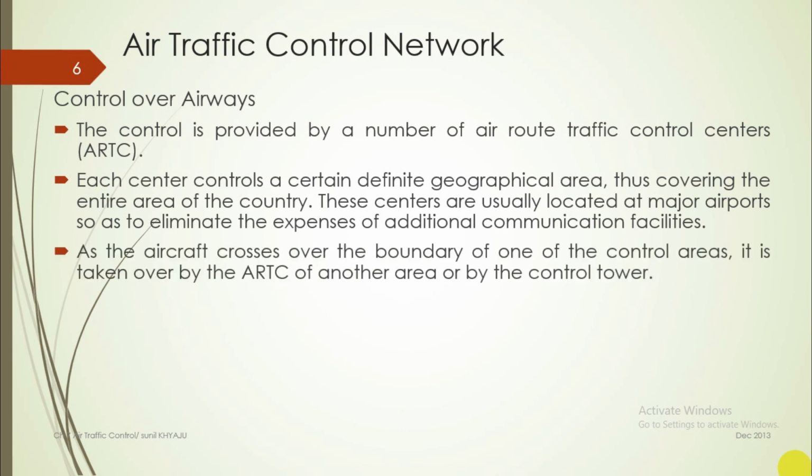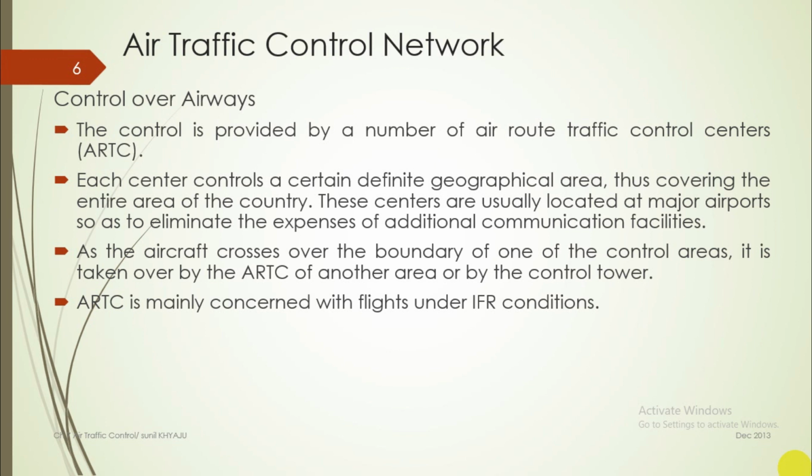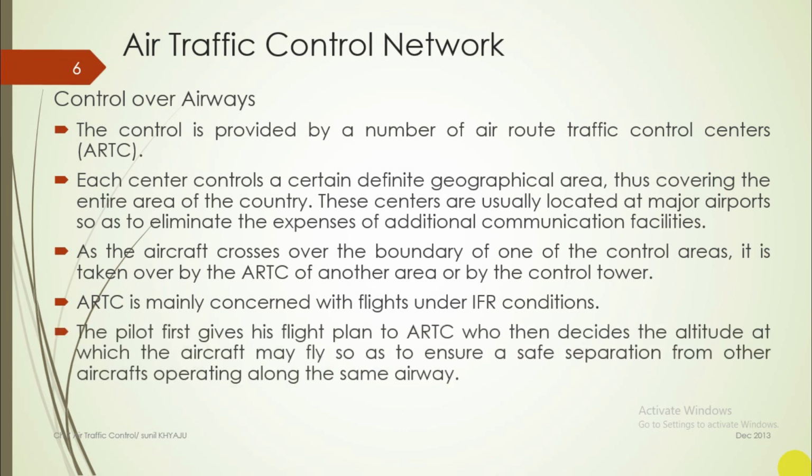As the aircraft crosses over the boundary of one of the control areas, it is taken over by the ARTC of another area or by the control tower. ARTC is mainly concerned with flights under IFR, Instrument Flight Rule conditions. The pilot first gives his flight plan to ARTC, who then decide the altitude at which the aircraft may fly so as to ensure a safe separation from other aircraft operating along the same airways.